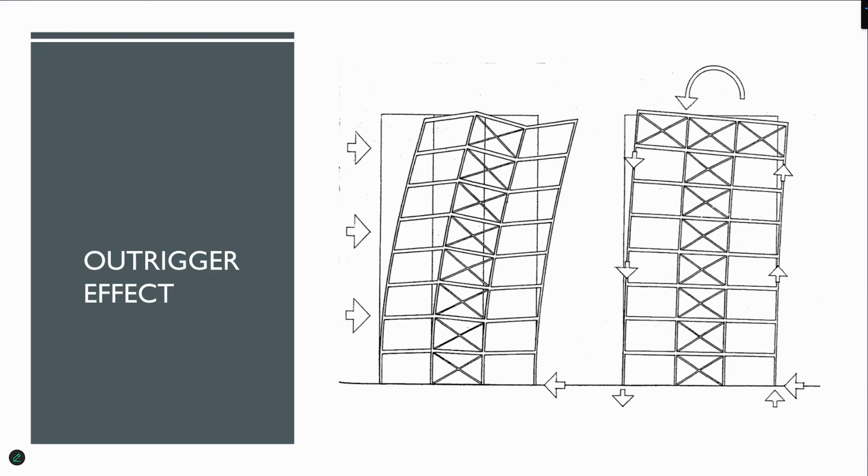the top level is no longer straight. And this effect is going to push-pull this column up, push this column down. One is going to be in compression, one is going to be in tension, and that tension-compression couple provides us the stability. We can also move this to the top like that, and the same thing happens. So this one comes in compression, this one in tension.